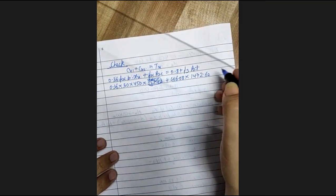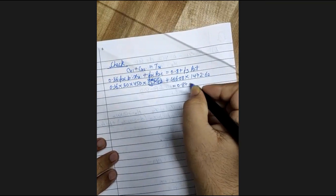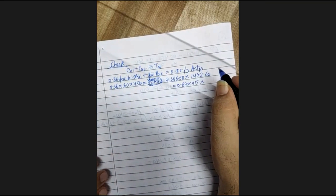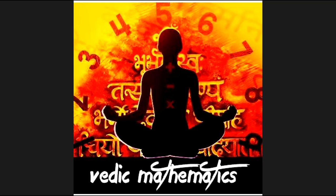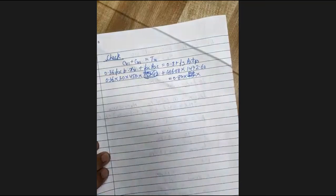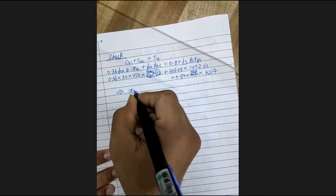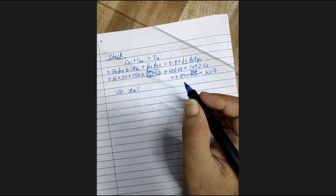Plus FSC into ASC is equal to 0.87 into FY. How much AST did we provide? 500 for one, so grade is 500. AST provided is 3217. So XU is coming 161.86.